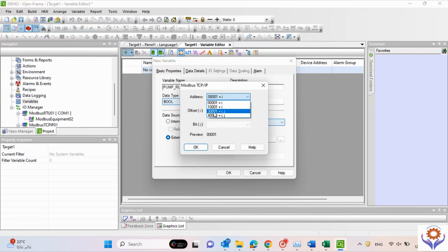But here also you have in the holding register, you have plus the, see, 3001 plus I plus J. Select this option. I will tell you what is I. See, 3001 plus I, what is your offset? Example 200. Because if you see our Unity Pro application, like introduction to Schneider Unity Pro, I already created some variables. I am linking that address here.